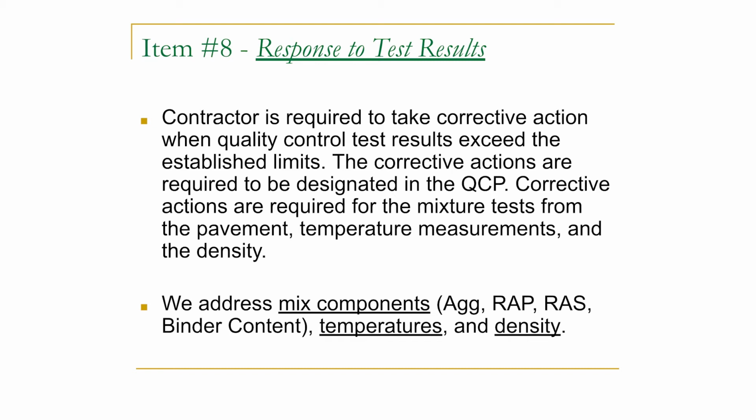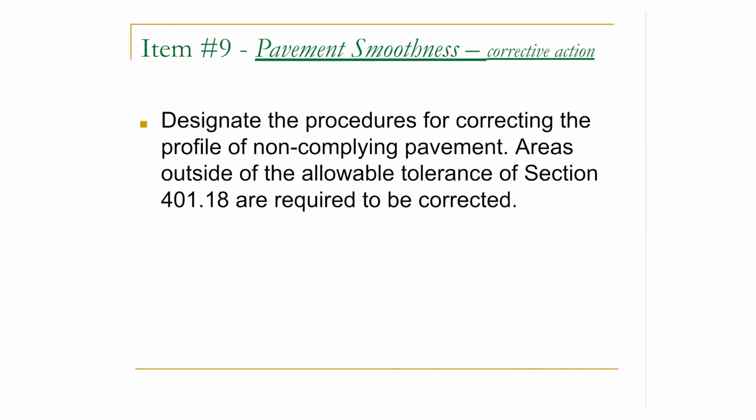Whether it's cold feeds or plant mix or roller operations that Jay talked about. So paving smoothness: how you're going to address your smoothness. Now coming into play and needing to be addressed is the IRI. We're getting away from the profilographs, so IRI is going to have to be put in these plans in the very near future.